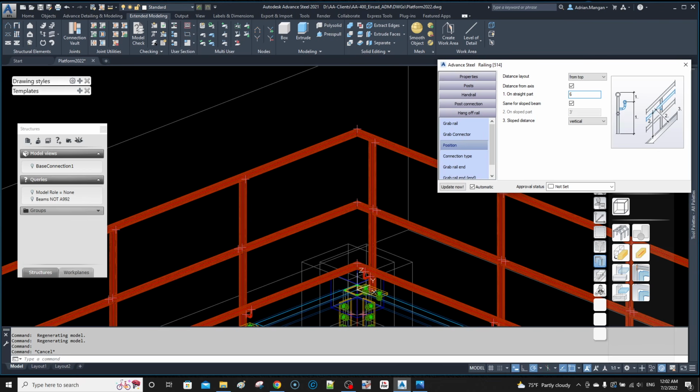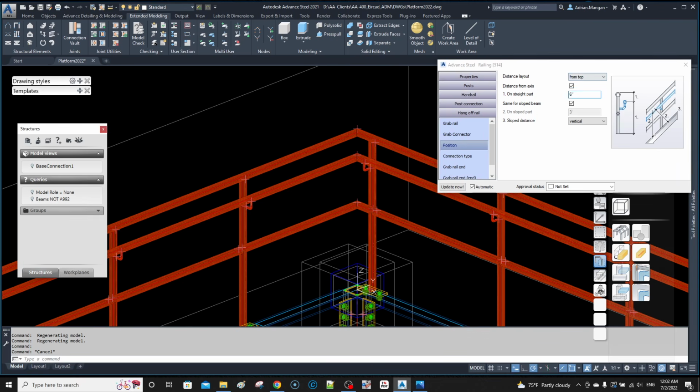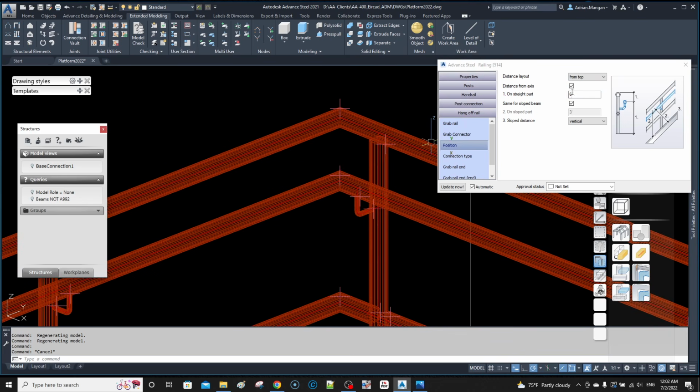Now the problem you're going to have here is, do I want it down 6 inches? Because it's going to go from the top of the rail to the center of this handrail. So it's really down 5 foot, or 5 and whatever, 1/16. So what I want to do is make this 5 and 15/16. So I have to take 15/16 away for this pipe. So it's going to be 5 and 1/16. That should be right. Not going to worry about it too much. I'm not going to start measuring it or anything.